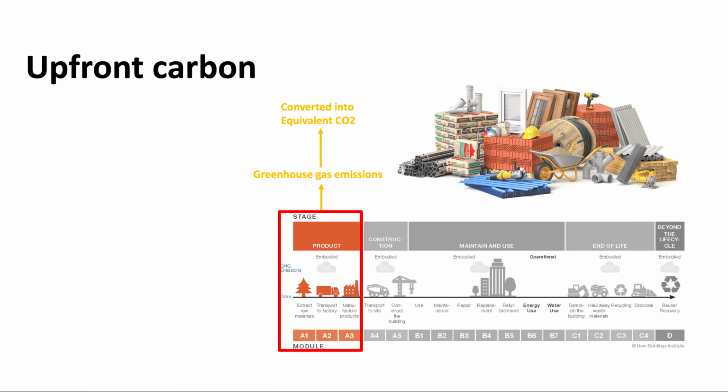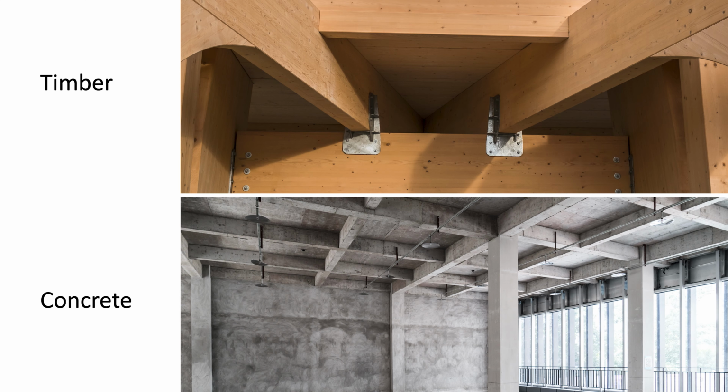As you might guess, every construction material has an embodied carbon figure or value attached to it, even before it is used in buildings. This is called upfront carbon or cradle-to-gate embodied carbon and includes all carbon dioxide emissions during the manufacturing processes of a certain construction material before the material is transported to the construction site. Upfront carbon varies from material to material.